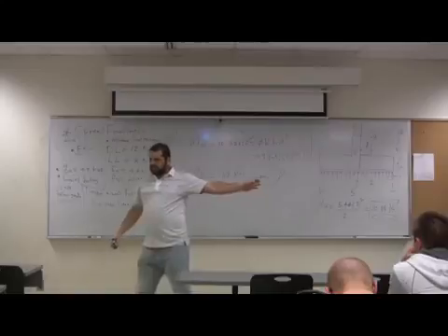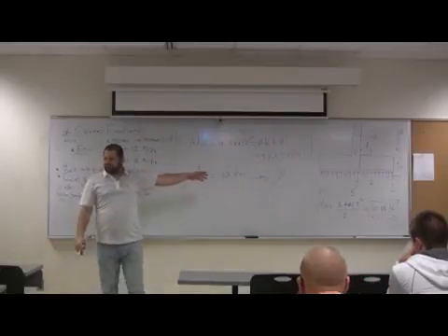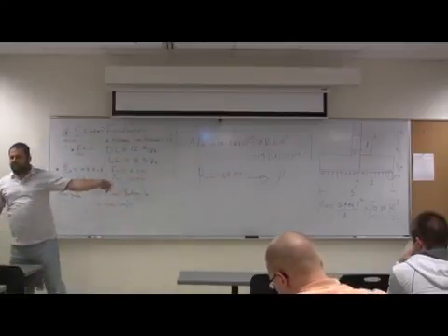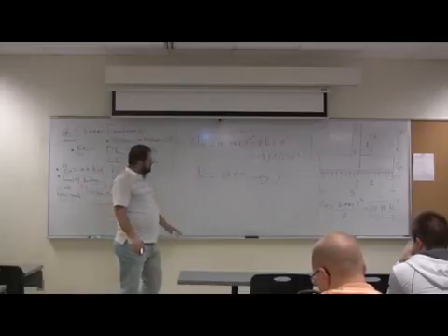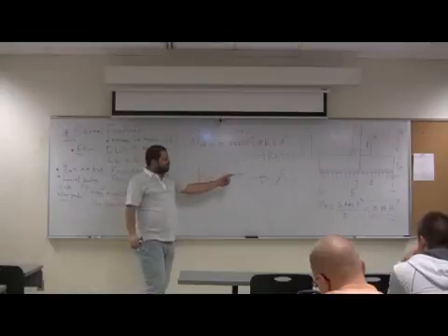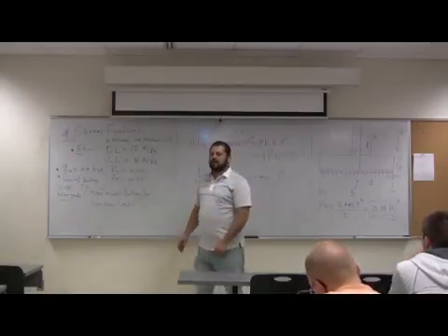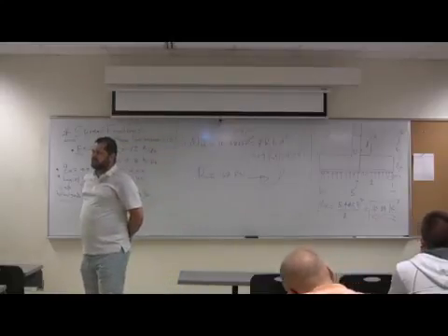Again, remember the other day, last lecture, I calculated using the typical method for the reinforcement. You can go with phi As Fy (d minus a over 2) and check a with the iteration method. Or do that. From the design aid, you will get rho for this R. You go with f prime c equal 4, Fy equal 60, and give me the closest.